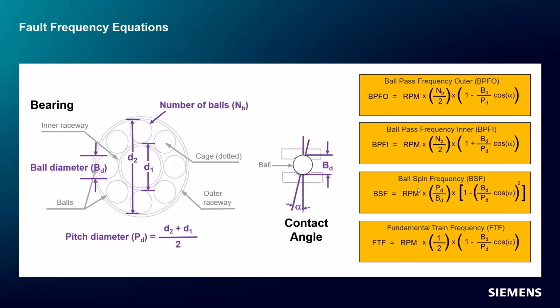So you can see these equations are complicated and they have things like the contact angle and everything else. If you normally get a bearing from a bearing manufacturer, they often will give you these fault frequencies so that you know what frequencies to expect from the bearing. Have you heard of these fault frequencies before, Steph?